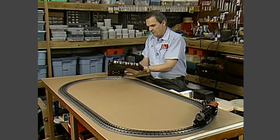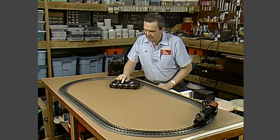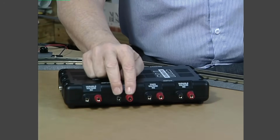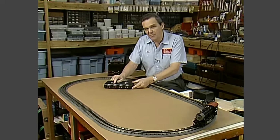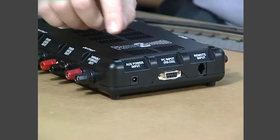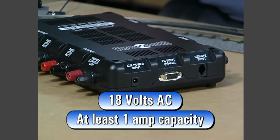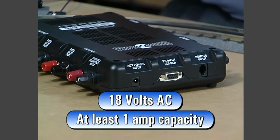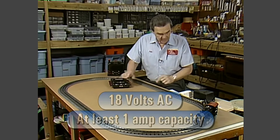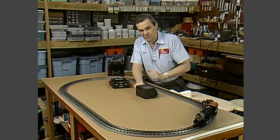The TIU has to have power in order to work, and it can be powered 2 different ways. It can be powered via the fixed in 1 channel. If you connect a transformer to this channel, as we did here, you're okay. However, there is a better way to power the TIU. You can also power the TIU by plugging a small AC transformer into this plug. Any small transformer that can provide around 18 volts AC at an amp or so will work here. The current draw for the TIU itself is not very high. The power brick from a Z500 or a Z750 is ideal for use here.